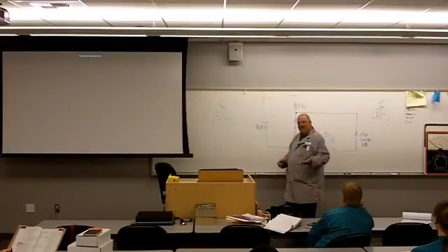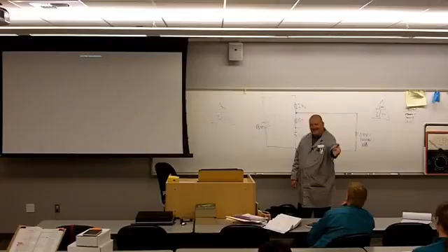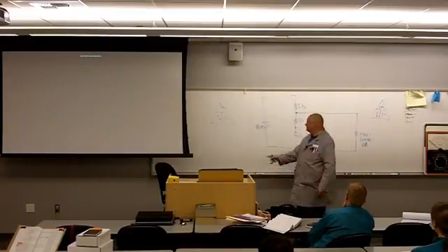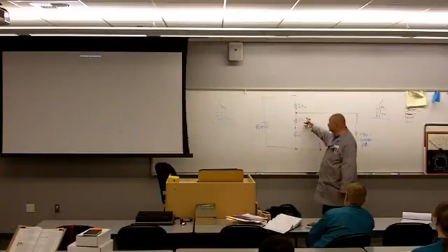Come on, guys. Quote me what I've been quoting you. Your drop has to equal the rise. Absolutely, because the drops have to equal the rise. I'm putting 48 volt rise in. I'm getting 48 volts a drop. 12 here, 12 here, 24 here. All voltage drops present and accounted for.